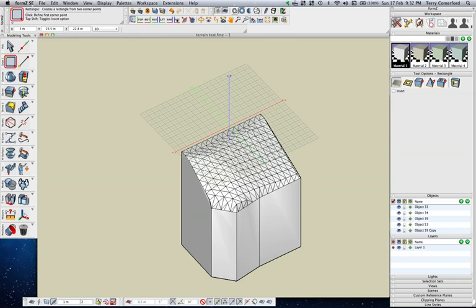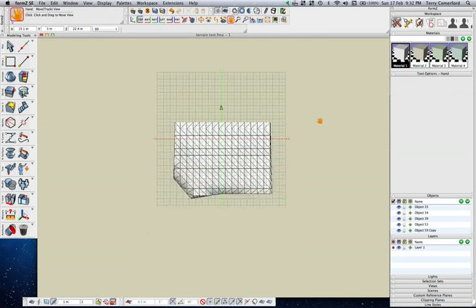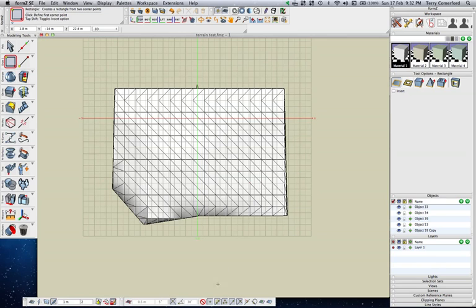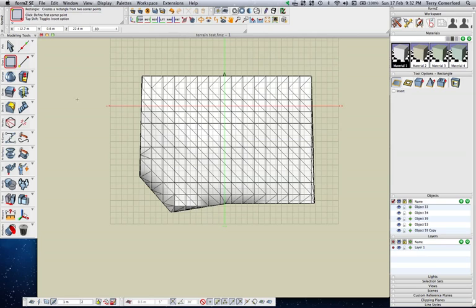So while that reference plane is locked, I'll go to a top view, so I'm looking straight down on my site, so I can start looking in plan view to plan where my building platform is going to be in a site plan view. Now, as I start to draw this shape that I want to be my site platform, so that I don't snap to any points while I'm doing this, come down to the bottom near all of your object snaps and press what I call the Ghostbusters sign, so that you won't snap to anything, and it'll allow you to free-form pick a point where you'd like your boundary to be. Let's say I want it to look something like that.